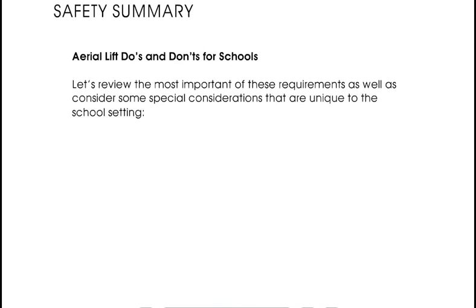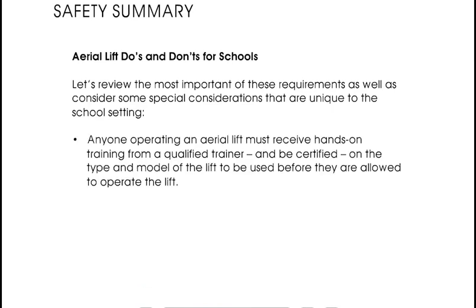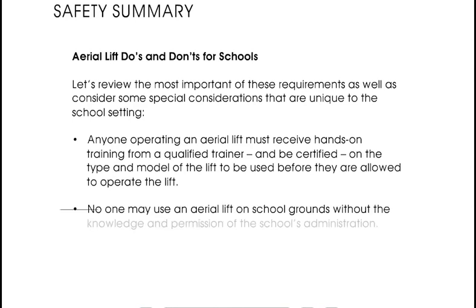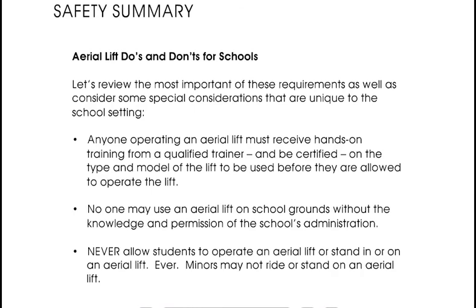Let's review the most important of these requirements, as well as consider some special considerations that are unique to the school setting. Anyone operating an aerial lift must receive hands-on training from a qualified trainer and be certified on the type and model of the lift to be used before they are allowed to operate the lift. No one may use an aerial lift on school grounds without the knowledge and permission of the school's administration. Never allow students to operate an aerial lift or stand in or on an aerial lift, ever. Minors may not ride or stand on an aerial lift.